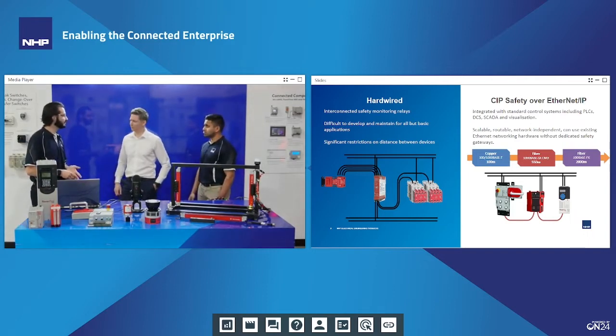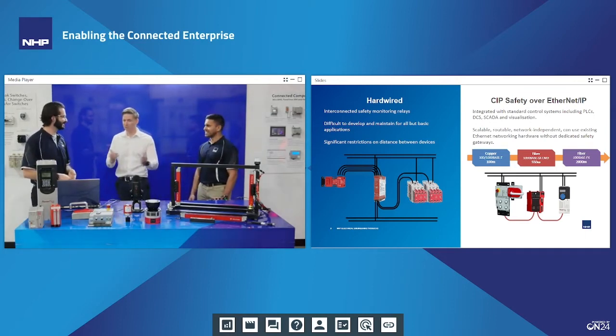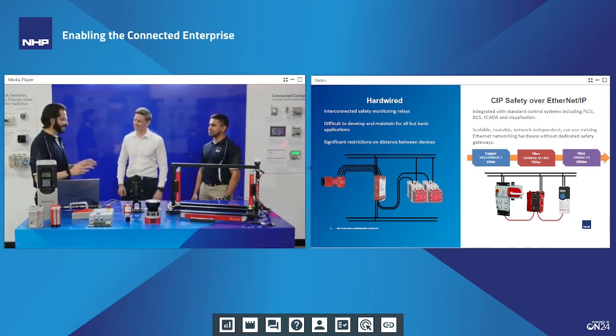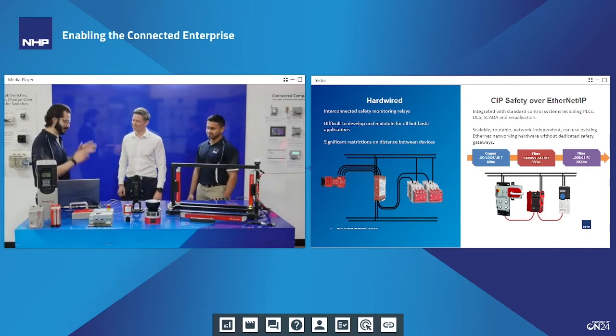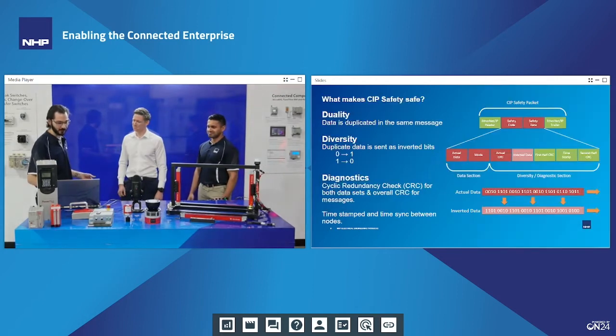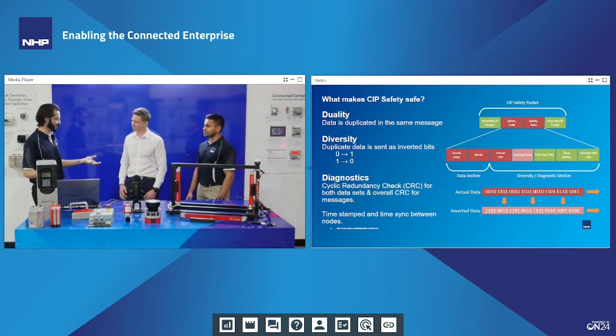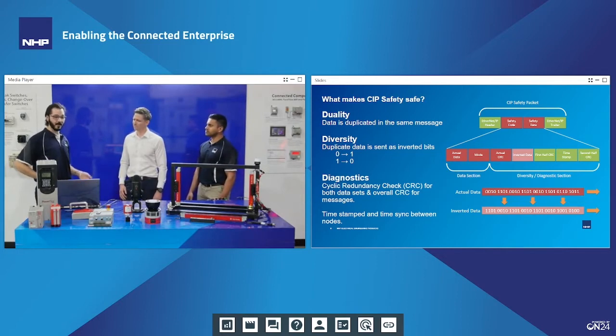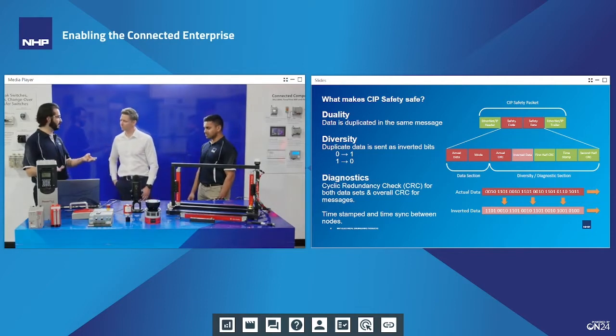Nice. I guess that's all well and good. Then the number one question no doubt everyone's asking or thinking, Dan, is what actually makes CIP Safety safe? Okay. There's a lot of detail that goes into the CIP Safety protocol that, frankly, we just don't have the time to talk about. But what I will go through is some of the fundamental aspects of what makes CIP Safety safe. You may have heard of the 3 Ds: duality, diversity, and diagnostics. These are incorporated into nearly every type of safety system, be it hardwired or in the communication space, which is what we're dealing with. So what do we mean by duality in terms of CIP Safety?